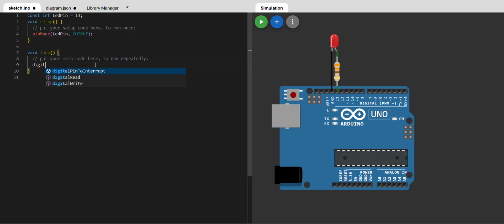Okay, it is digitalWrite. It is enough to declare only one time as an output, right? So I have mentioned the pinMode function, or the method, in the setup function. Only one time if we declare it as an output, then until we declare it as an input or any other type, it will be treated as output only. So we need not tell it every time, right? So I have declared it in the setup.